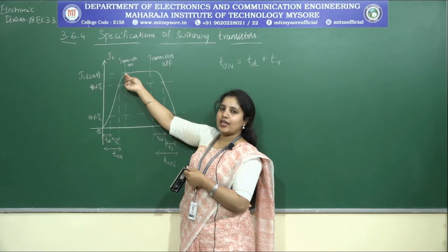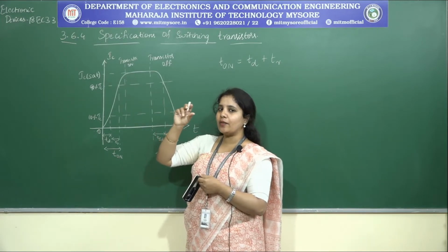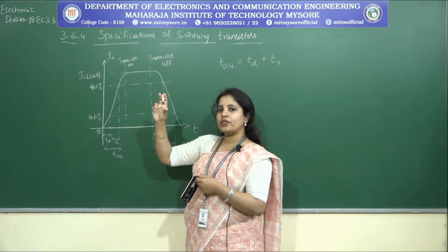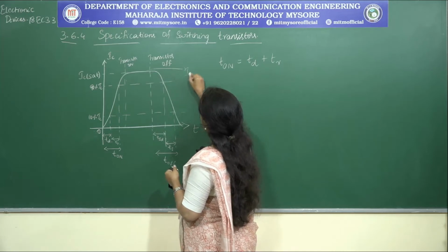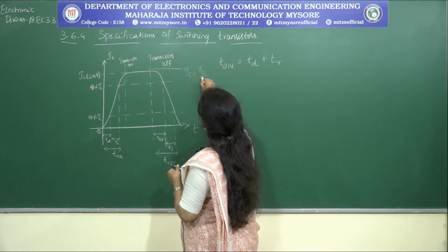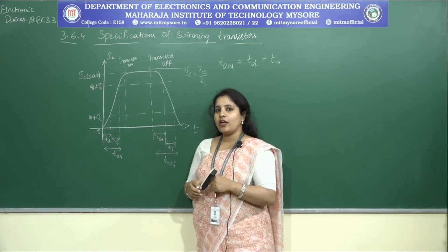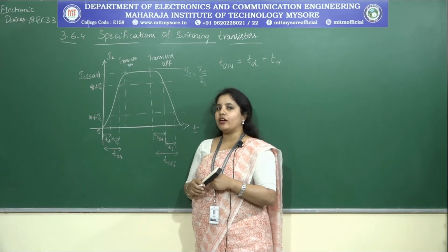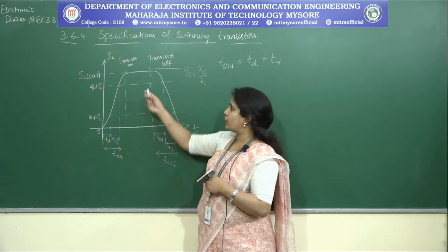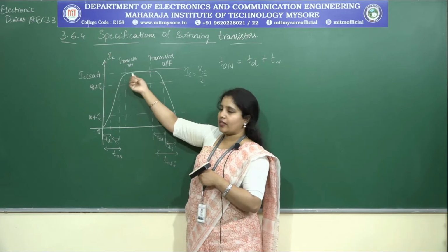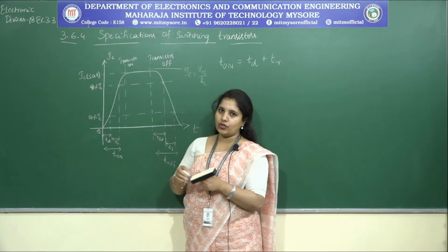When the device is in the saturation region, what is the drop absorbed in the collector junction? It is very minimal, right? So, all the drop is absorbed across the load. Therefore, how will I represent this current? IC, if you remember, is represented as VCC divided by RL. And in the previous case, by considering 40 volts and 5 kilo ohm, we got around 8 milliamps of current. So, that is how we get the saturation current, the maximum current that you can achieve across the collector region.